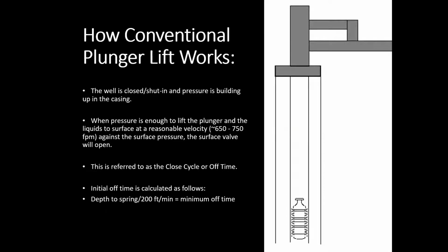So next we'll discuss the plunger cycle process of plungers. The motor valve is closed to stop the flow from the wellbore down the flow line. Since the flow is stopped, the plunger begins to fall from the lubricator at surface to the bumper spring. We'll discuss different fall speeds later in this presentation.